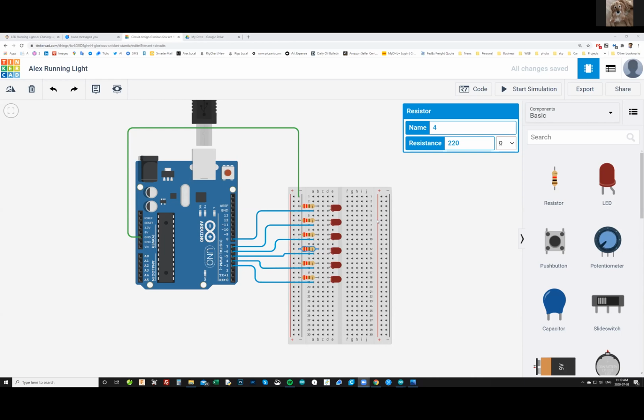Guys, with LEDs, the one thing I noticed just now is when you bend the longer leg, the distance between them is definitely more than just one hole. On Alex's diagram it's always the next hole, but in reality, it can be a gap of 2 or 3 holes, like here. Exactly. You can put your resistor this far apart and put it like that.